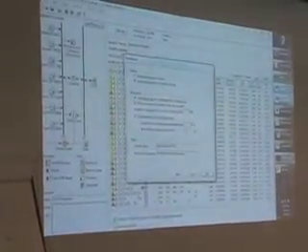So Peter, in this case, the time interval was 1 hour. If we were to change that to 15 minutes to really, say, correctly model the flywheel, would that automatically change to 15 minutes, or would that still stay 1 hour? No, you'd need to come in here and change this yourself.